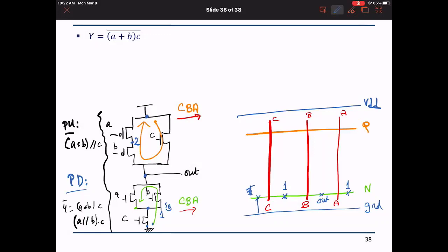Okay, now we go back to B. We are starting here. We are starting from VDD. We go through transistor C to node out, which is a common drain between B and C. We cross B. Okay, we reach node 2, which is between A and B. And then we visit A and we go back to what node? VDD. Okay?